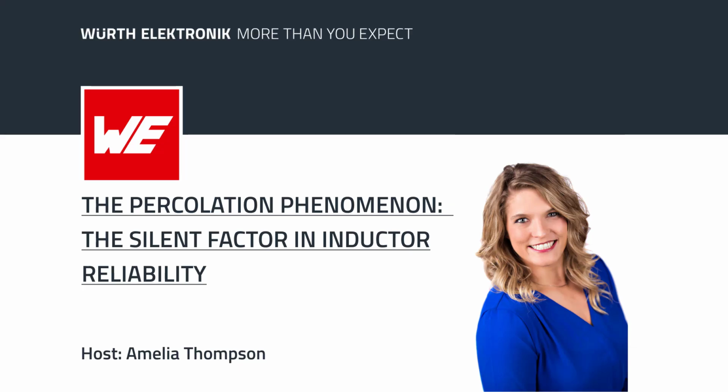Now, recently, our team of engineers at Würth Elektronik has started dissecting the new term that they've coined, percolation. The percolation effect is a phenomenon that occurs when there is elevated voltage and temperature over time on molded power inductors in a DC to DC converter. In this episode, we are covering not only what percolation is, but more importantly, how it affects the long-term performance of a DC to DC converter.